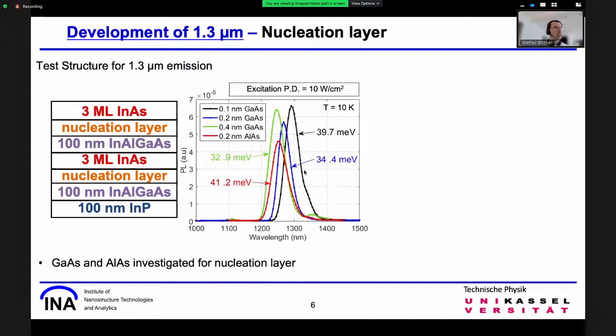Okay, thanks. Frederick? Just a quick question. Have you tried already to fabricate ridge lasers? Yes, we have already fabricated ridge waveguide lasers, and it already shows a large improvement. I couldn't show this in the presentation right now as it was done just this week. For the initial laser, we had around 50 Kelvin and 70 Kelvin for T0 and T1 values, while right now, we have around 241. Okay. So it's already a large improvement, yes.